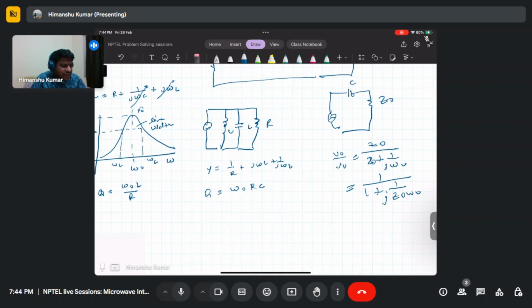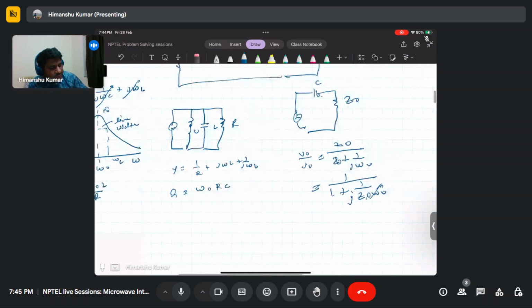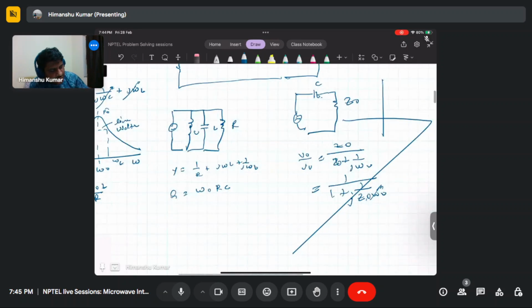as you have very high frequency, then for high frequency V out will be equal to V in. So basically, this will pass. This will behave like a short circuit, and all that power will be transferred to the load. And at low frequency, the capacitor will block, and you will have the response like this. So it will behave like a high pass filter, right?